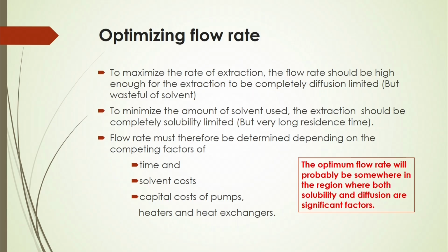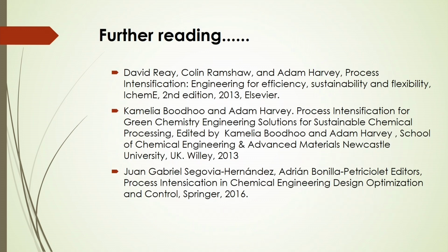Flow rate must therefore be determined depending on the competing factors of time, solvent costs, and the capital cost of the pumps, heaters, and heat exchangers. So, the optimum flow rate will probably be in the region where both solubility and diffusion are significant factors. These are the factors you have to consider during the design of the system, and case to case you have to take care of those optimizing conditions to get a better yield of the extraction process in an intensified way.